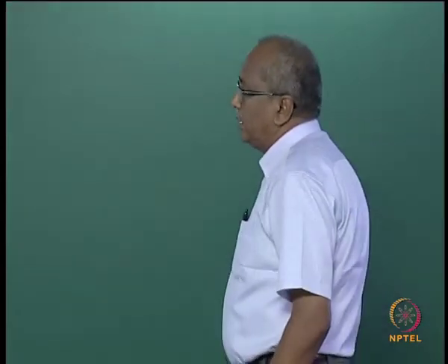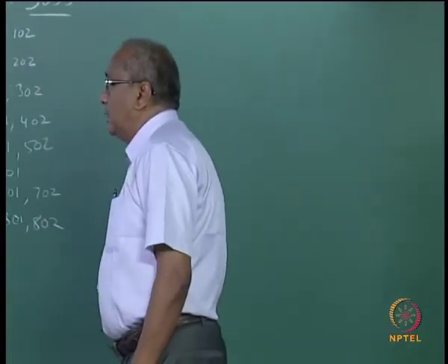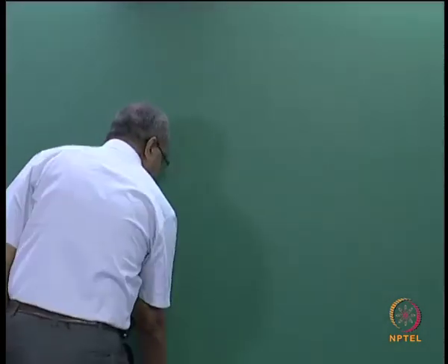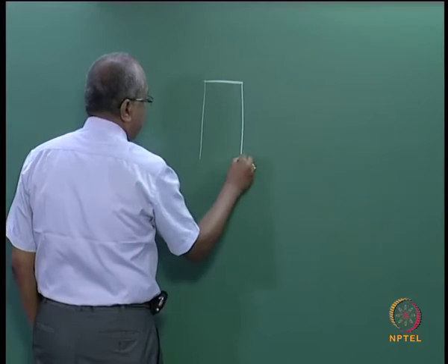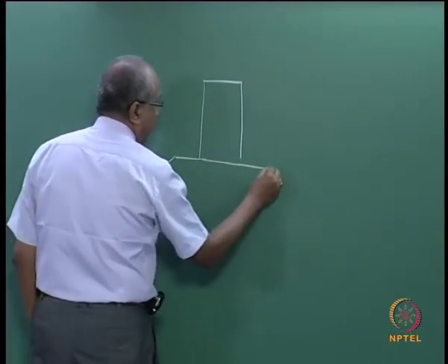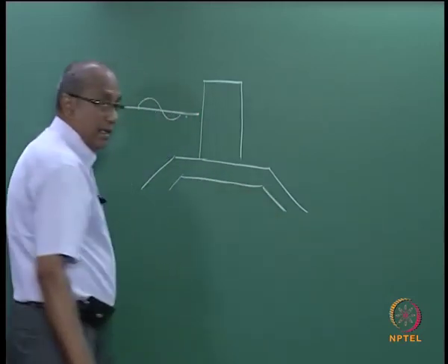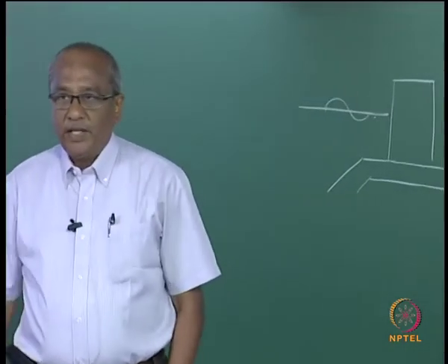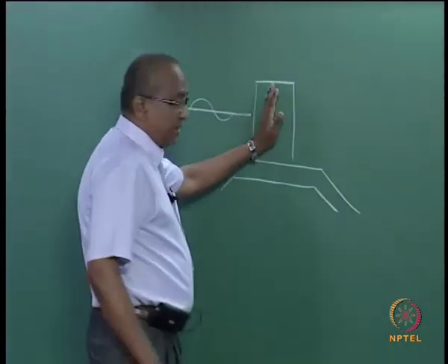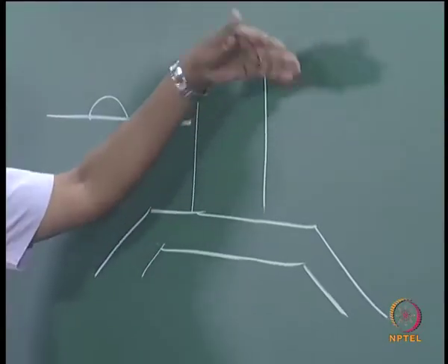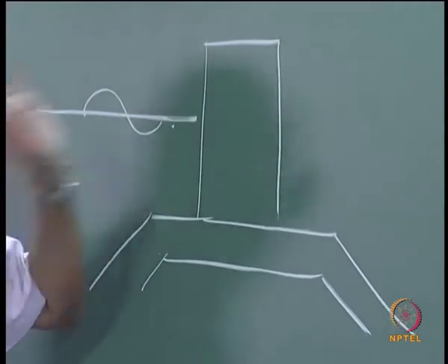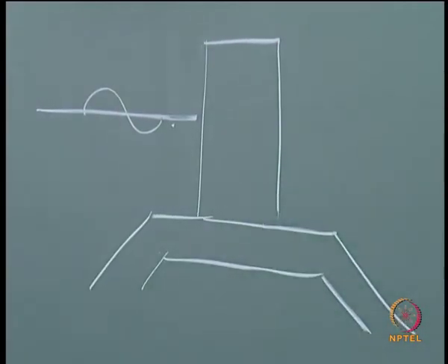Having seen the vertical composite breakwaters, now we will go into the horizontal composite breakwaters. The wall of the vertical composite breakwaters suffers damage, because although it is a gravity type of structure, it is resting on a rubble mound base. But if there is excessive force acting on this structure, there is a possibility that overturning can happen, and it can be a sudden instant failure.